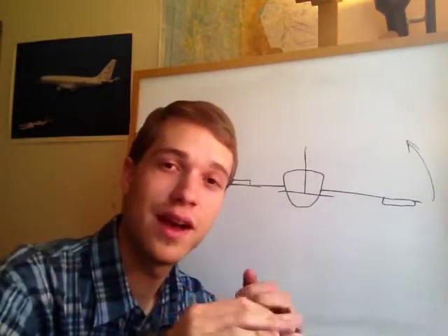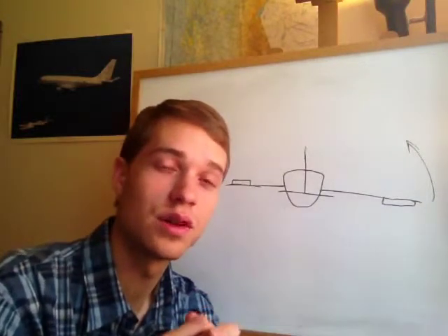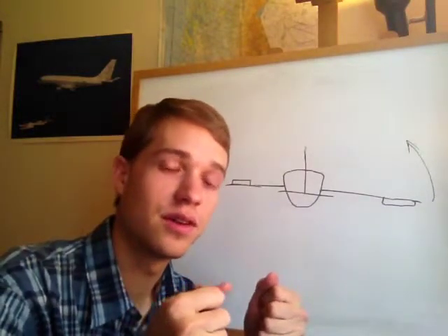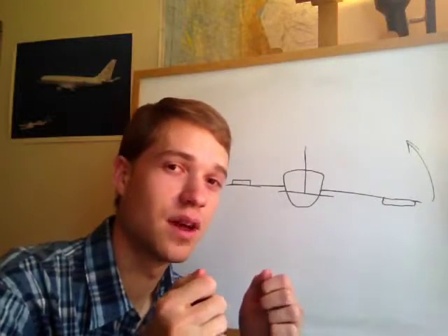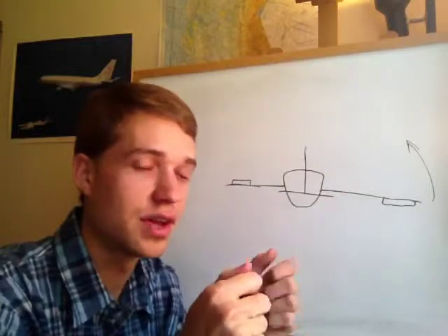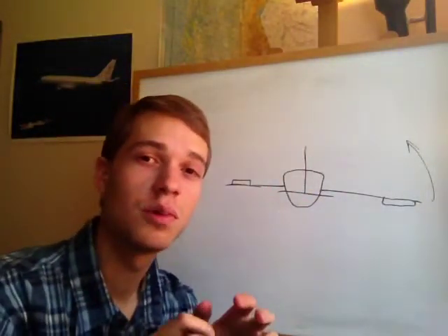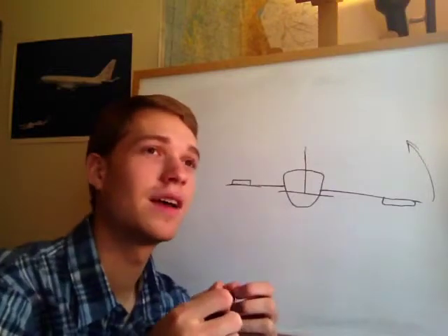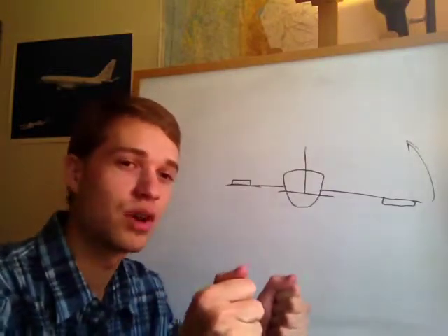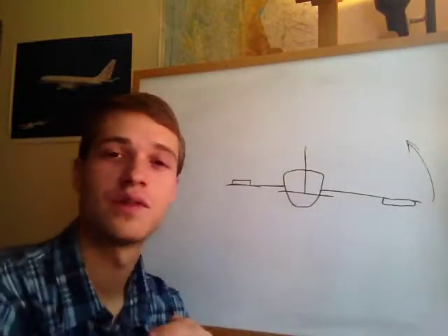The faster you're flying, the faster the air is flowing over the control surfaces, and so you're going to feel the controls firm up as you get faster, and it'll take less actual movement of the controls to produce a big reaction from the airplane. And so we don't fly control movements, we fly with control pressures. We exert pressure on the controls, just enough pressure to get the right response from the airplane.